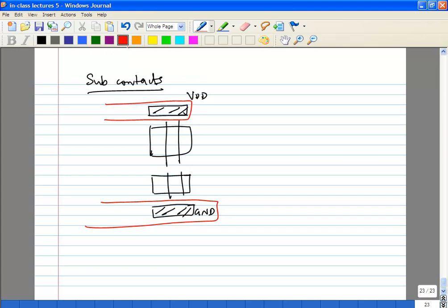It would look like this. But if your circuit is sensitive, you may also want to put in contacts here on the sides, because you want to give a really good substrate. Remember that a lot of transistor parameters depend on the substrate, things like threshold voltage. If there is any substrate current, and there will always be some RF current being sent into the substrate, what you will see is if the substrate has some series resistance, that will build up a voltage, and if your substrate voltage is wiggling, then your transistor threshold voltage is changing over time, for example.